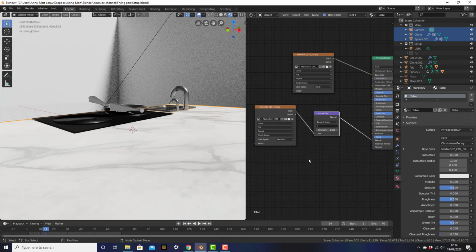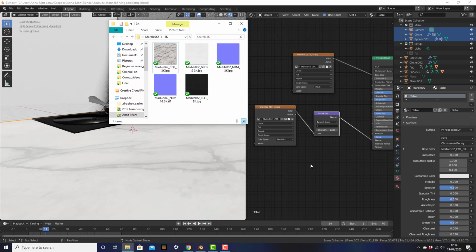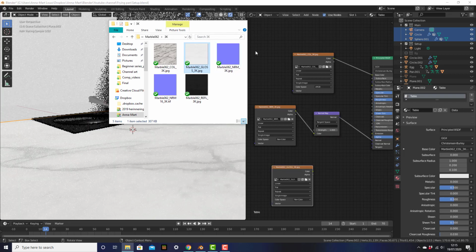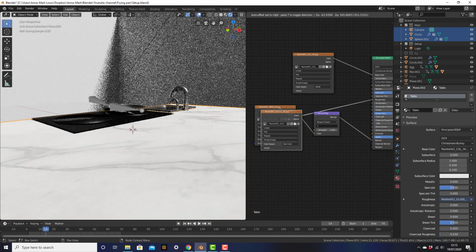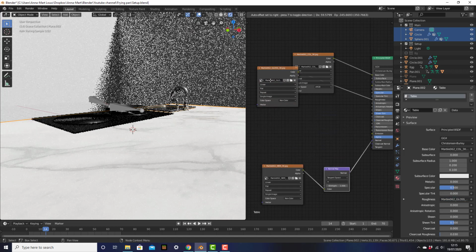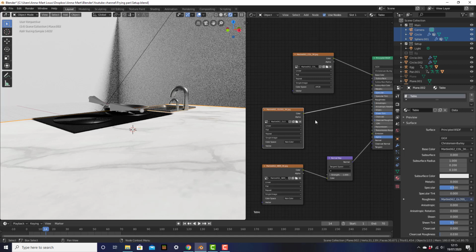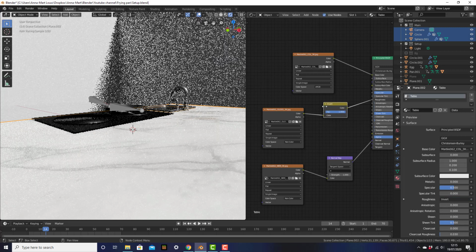And this will add some of the texture to it, so that it's not just an image that's pasted on top. Now we also want to add the roughness, but when we downloaded the files, they didn't have a roughness map. But luckily, a glossy map and a roughness map is basically exactly the same thing, but they are just inverses of one another. So if we add a glossy map instead, and connect it to roughness, let's just move these around. All we need to do is add an invert node. So to do that, we just say Shift A, and then click on the search button and type in invert.